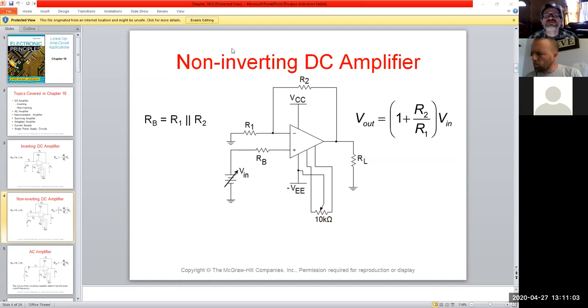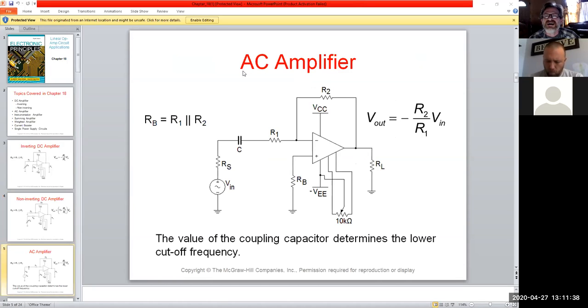And you've got your offset null. Same deal. And this is a full pin out. That's why I like the Malvino models, because he shows you the whole full pin out. If you count them up, you would get 7, and this is an 8-pin IC, so one of them is literally unused. If you look on the spec sheets, you'll find it. There might be a couple out there that have some strange deal with pin number 7, but in most cases that's an unused pin. It does literally nothing but take up space. All right.